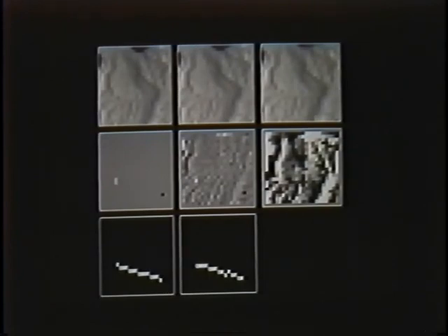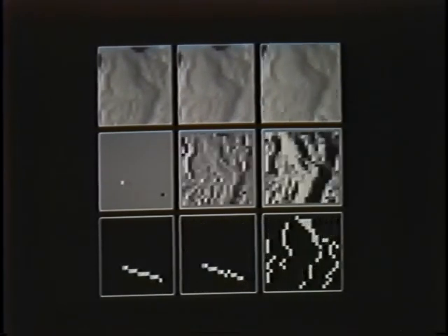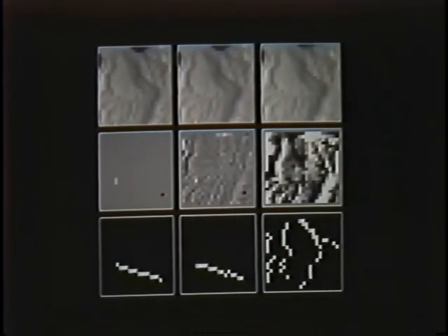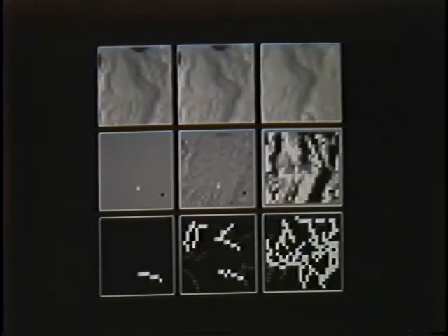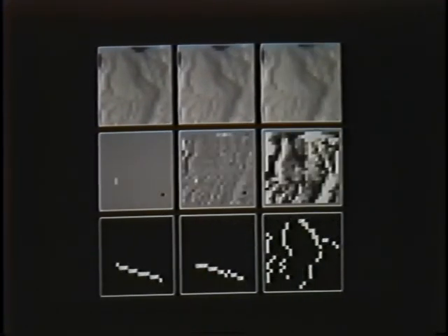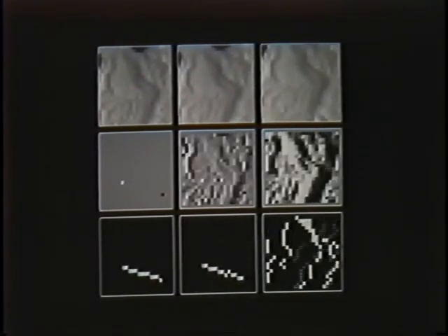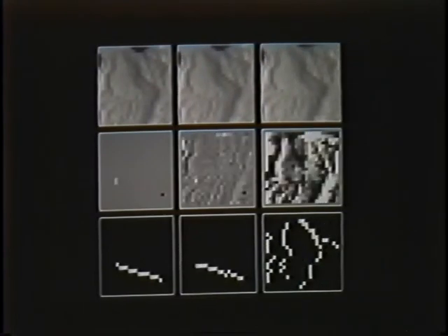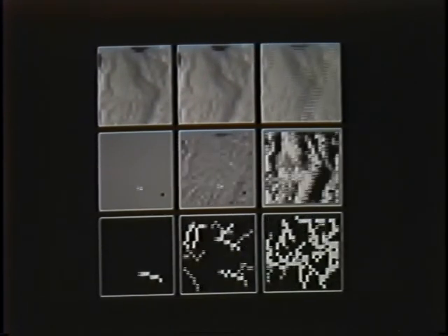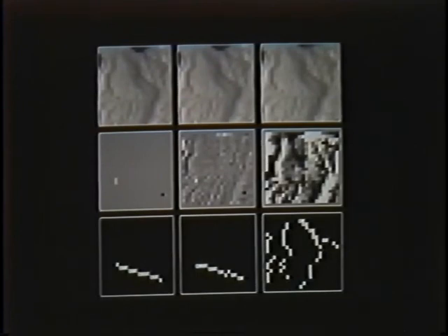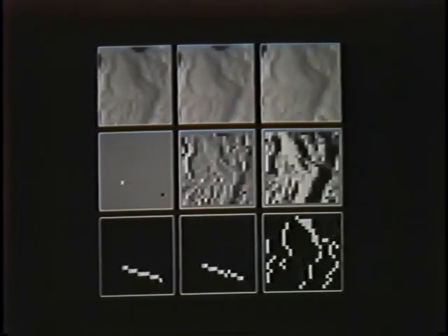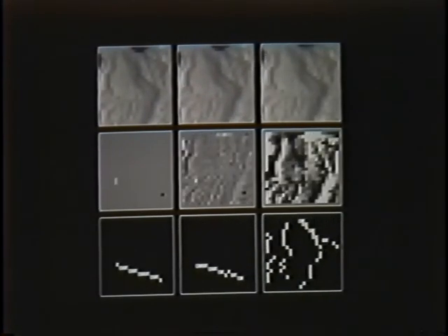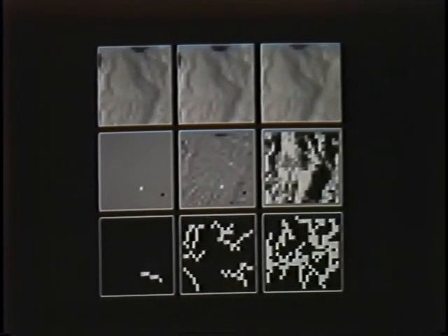As predicted, the tracks algorithm was unable to detect any sign of the target in the big jitter sequence after it was differenced. In fact, it calculated that some false tracks looked more like the target than the real thing, and wrongly determined them to be targets. Although we can't see the target in the original big jitter sequence, it is there. As was shown in the no jitter and small jitter sequences in a relatively stable background, the target was strong enough for detection. But when the jitter got too large, the target's signal was overwhelmed by the clutter noise, and simple frame-to-frame differencing was unable to bring it out.